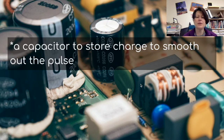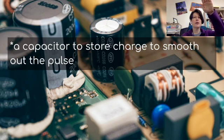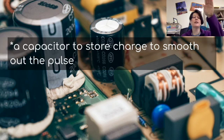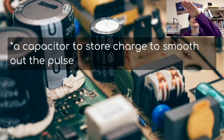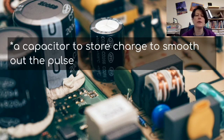So, what they do is they also add a capacitor to store charge to smooth out the pulse. Now, capacitors just store charge. So, what it does is instead of having those bumps, there's a bump. The capacitor lets out energy until it gets to the next bump. It stores some energy, lets it out gradually to the next bump, stores energy, lets it out gradually to the next bump. And so it evens out that signal.